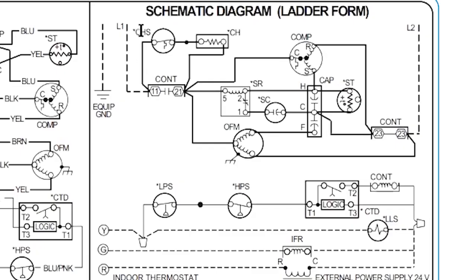All right, so now how does this work here? I've done a separate video on the crankcase heaters. Actually, I didn't do a video on this one. I did a video on the capacitor type. But basically, without going into it, this crankcase heater will only work if the temperature is low enough that the switch is connected, so it hasn't risen and opened the circuit, and if this contactor is actually open. If this contactor is closed, there will not be a voltage drop between 11 and 21, and if there's no voltage drop between 11 and 21, there can be no current that moves through this circuit.